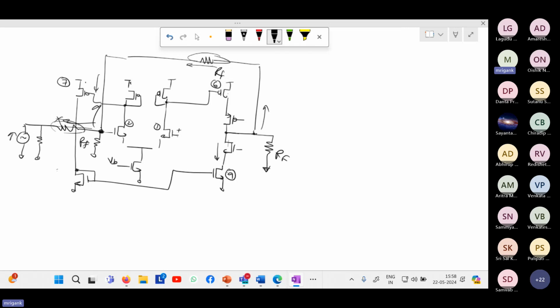So in shunt feedback, effectively this RF that is coming from output to the input, you will have an effective loading effect of the RF. So that is also another reason why we avoid using resistive feedback, because with resistive feedback you will have a loading effect and that is going to reduce your overall small signal gain. And one thing was the DC biasing becomes more complicated, but the loading effect is also another issue.